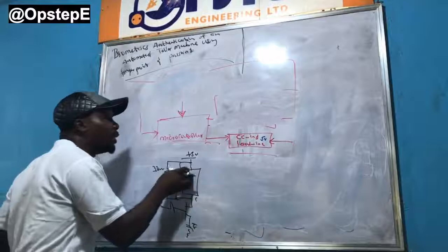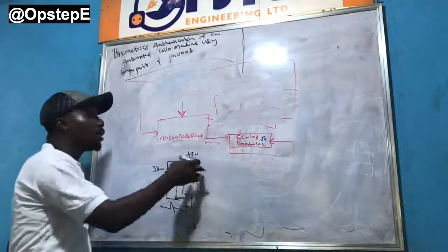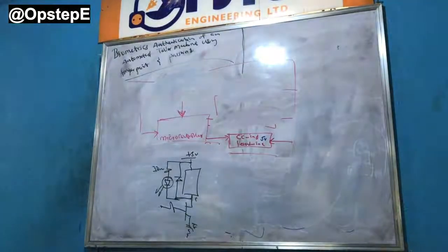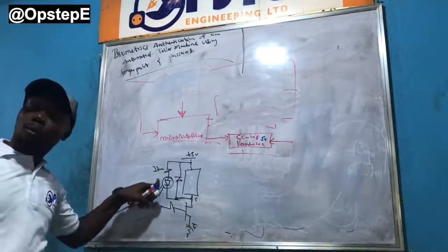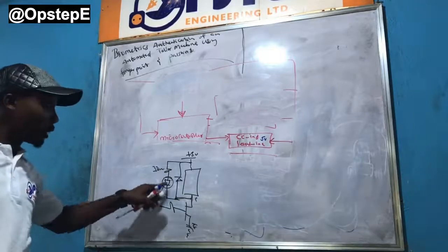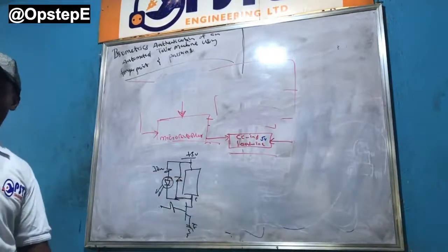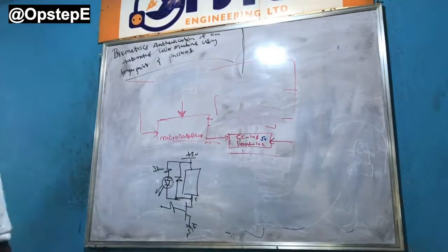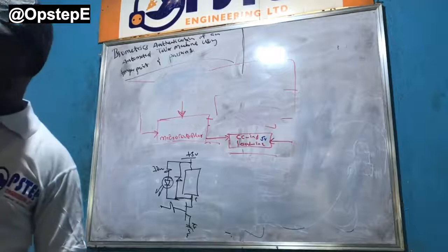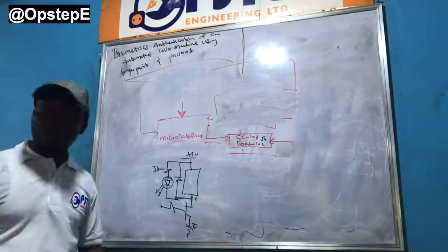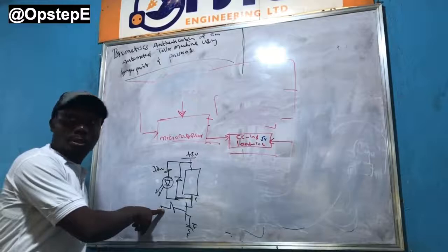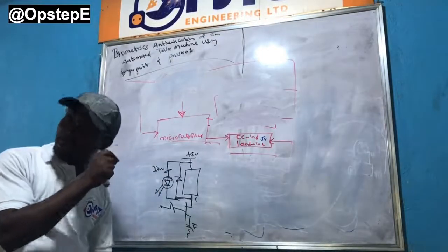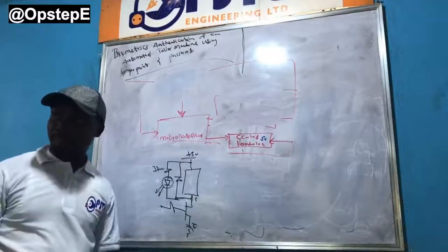So even if the relay is not the type that makes sound when it closes and opens, with this light emitting diode going on and off, you can tell if signal is going to the relay. So I actually put that in every time. It's not important, but it's good for debugging purposes. When I'm done with my board, I just fire this pin to see if this light comes on, and I listen for a click. So I know the relay is working.